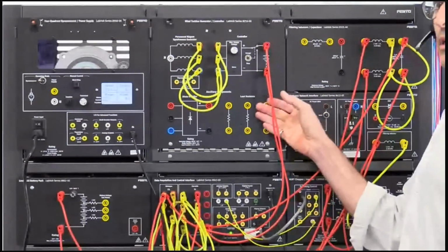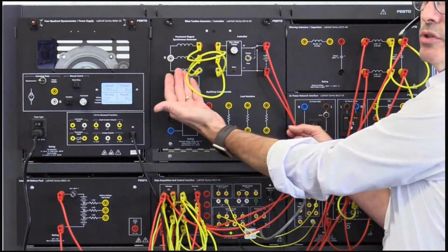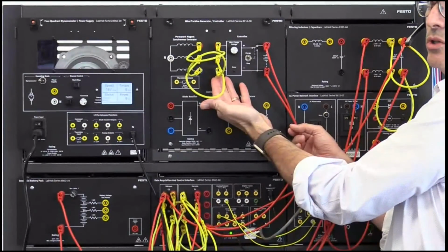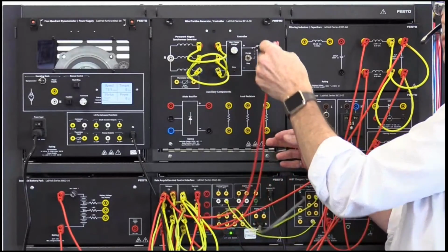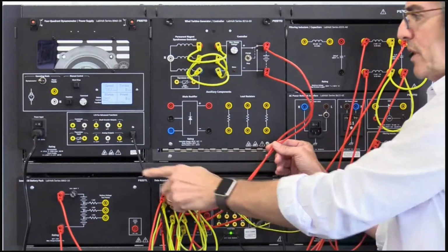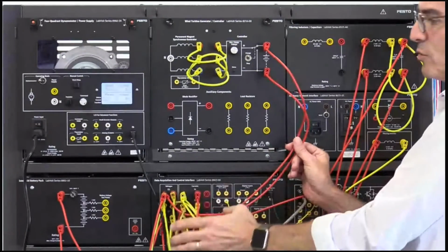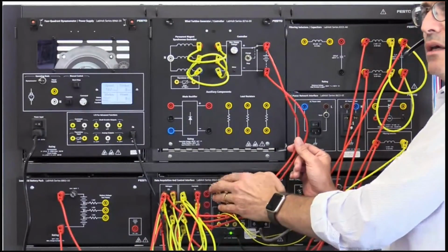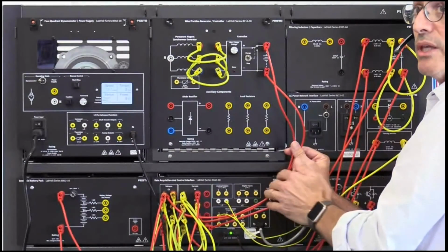First of all, starting with our wind turbine that I've just shown you, you will see that I'm connecting the output of the generator to the input of the battery charge controller here. So I will be able to charge my battery. Then on the other side, of course, I need to connect my battery. But first, before going to the battery itself, I go through this module here, which is our data acquisition module. That's why there are so many wires connected here, because this is the module where we connect our voltages and currents to be able to measure them and display them in our software.